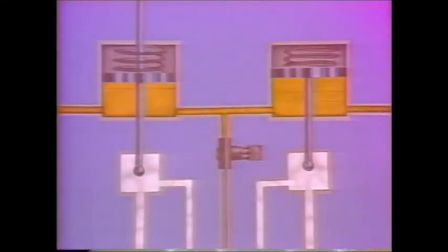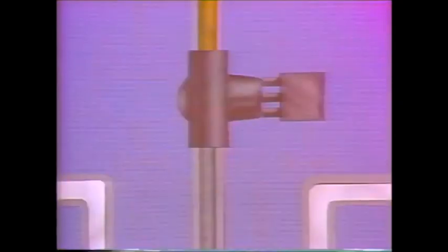In this simplified system, we're showing only two actuators, one for a control valve and one for a reheat stop valve. In an actual system, there is usually one actuator for each of all four types of valves. Here's the trip valve. When a trip occurs, it opens, dumping oil from all the turbine valve actuators, causing the spring action of the piston to shut off all steam to the turbine unit.